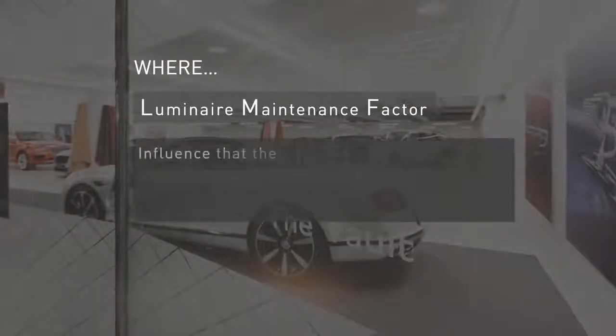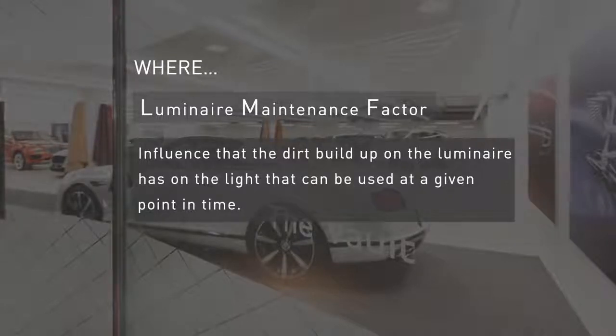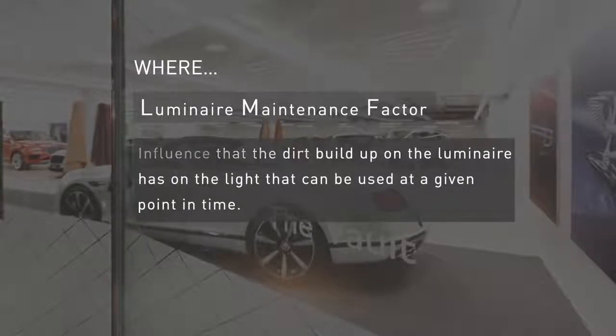And then we have the luminaire maintenance factor. Now this is the more complicated element where you have to try and predict how much dirt or dust might land on the luminaire and affect its light output over this period of time. Yeah, the guesswork is taken out of this to a fair degree because there are documents and tables which allow you to work out, given the project detail, what it is. We make a lot of assumptions, so we use that within the calculation. That's not to say that's definitely what will happen, but it helps us have a base unit that everybody can use.